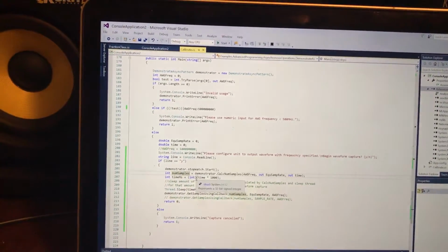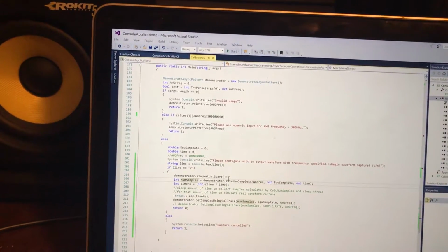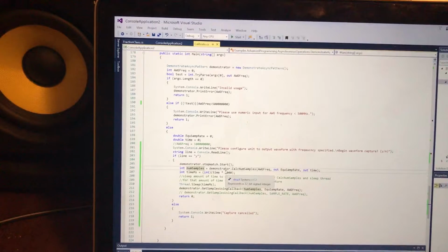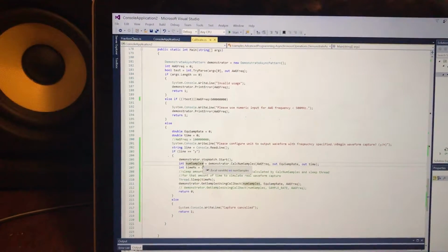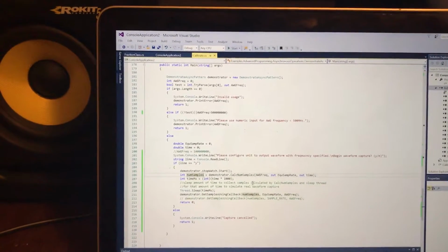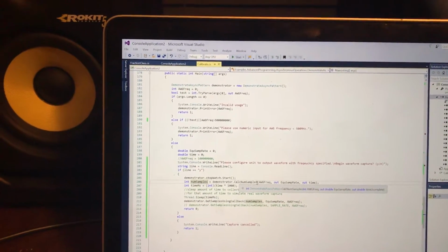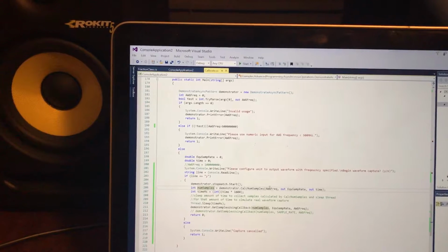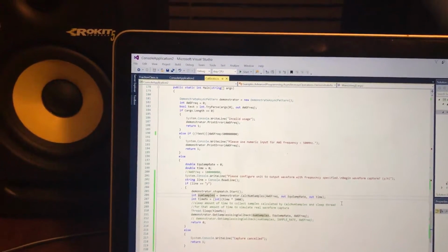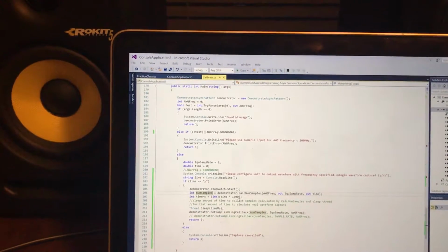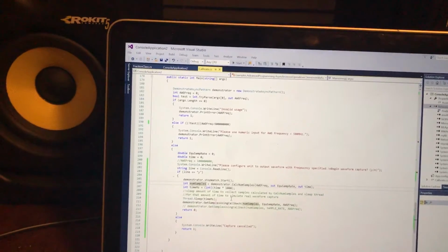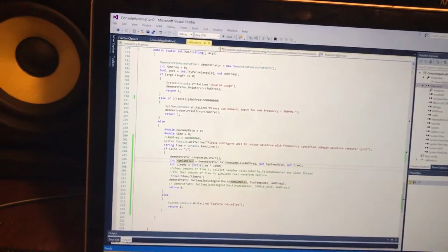Down here we start a timer to make sure that we're within time, and then here we calculate the number of samples that we will need based on our fractional n sampling method. This function also calculates the equivalent sampling rate given our AWG frequency and the sampling rate of our clock, which is constant at 10 megahertz plus 1 hertz.